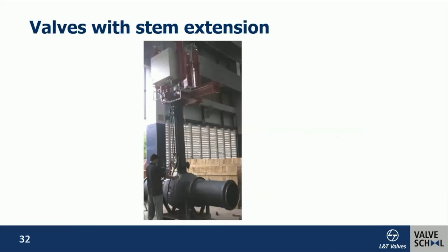This is a typical example of a valve with stem extension, which I mentioned, with a welded body design. If you can see the picture, the welded body design is on the valve, but these valves are also provided with pup pieces so that the welding of the valves with the pipeline is at quite a larger distance from the seat area. And if you look at this, the stem extension which is provided ensures that if the valve is buried up to a certain height,